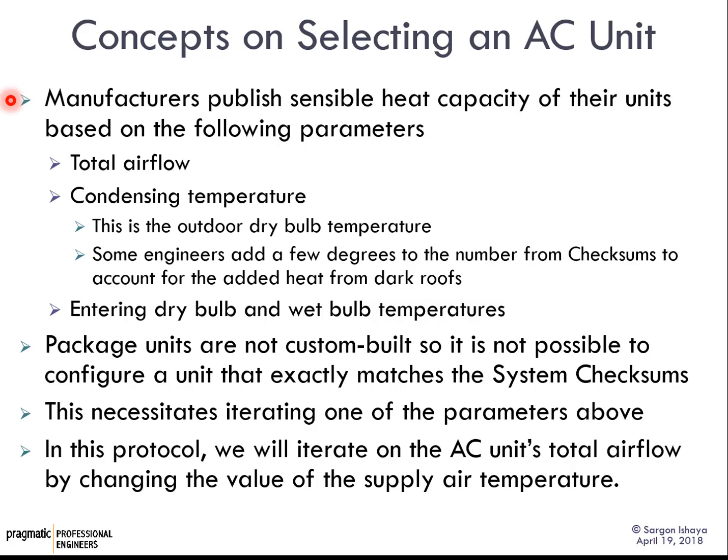Now we have to find a package unit that matches this load. Manufacturers publish the sensible heat capacity of the units based on airflow, condensing temperature, meaning the outdoor air temperature, and the entering dry and wet bulb temperatures of the units. Okay?